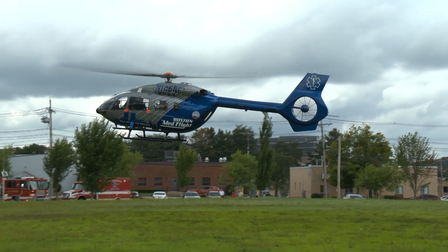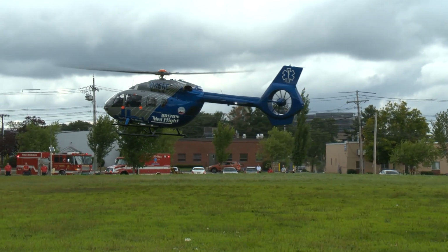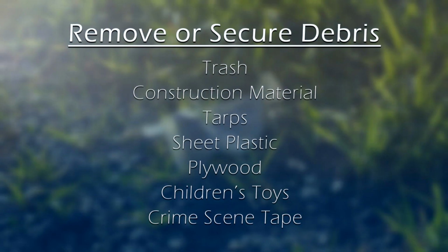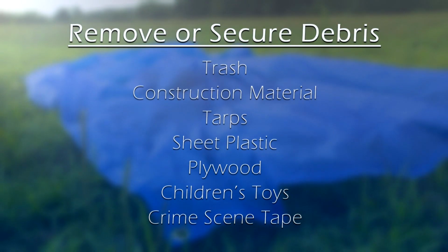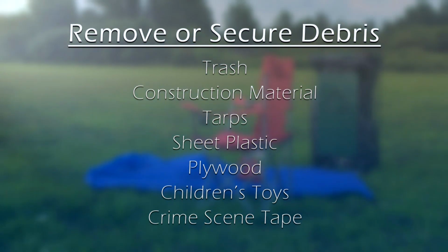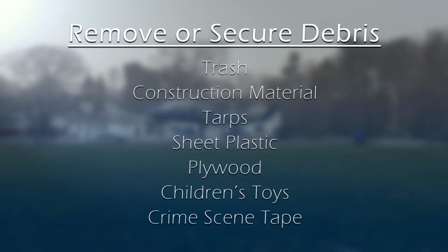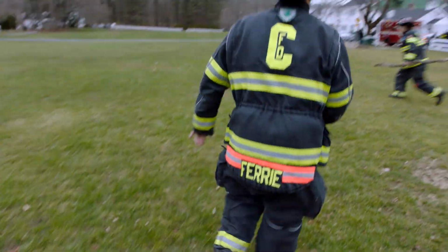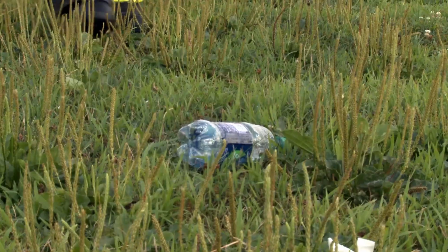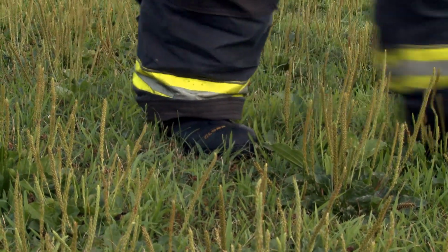A helicopter can generate winds in excess of 100 miles per hour. Debris in the surrounding areas, such as trash, construction materials, tarps, sheet plastic, plywood, children's toys, or crime scene tape, can be picked up by rotor wash and become a projectile. To avoid a potential safety hazard, all debris must be either removed or secured prior to landing.